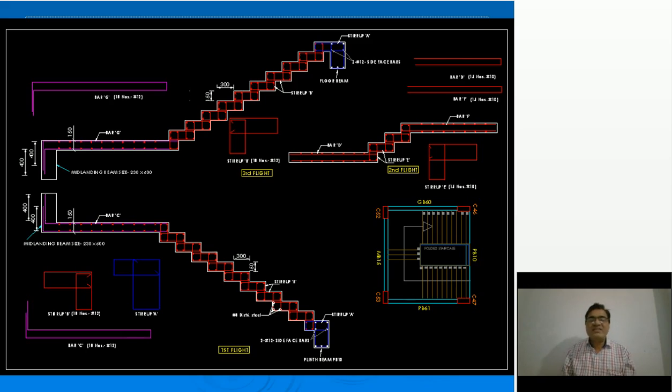In a folded staircase, the reinforcement detailing is totally different. You will not find continuous bars. In a dogleg staircase or open well staircase, we saw that continuous bars are provided at the bottom. Here you cannot provide continuous bars. Rings are provided instead. These are the detailing of the rings: the red color ring and the blue color ring. The blue color ring is the ring which starts from the beam. Then each step is made up of an L shape, for the tread and riser, and in that a ring is provided. Through the connected rings, the load is transferred from the flight to the adjoining beams.